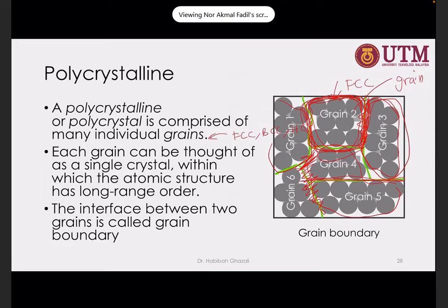So there are two different crystals. Both are crystals, one is single crystal, one is polycrystal. Polycrystal is easy to produce. If you have a liquid and you want to solidify it, you can design how many grain boundaries you want: too many grain boundaries, fewer grain boundaries, small grains, large grains. However, for single crystal, it is a very critical process, because they want to design something with less potential for failure. But inside the crystal, yes, both can contain FCC, BCC, or whatever crystal structure.